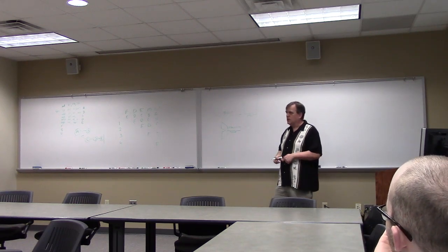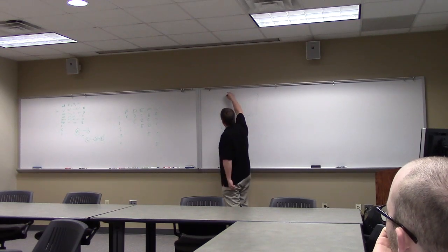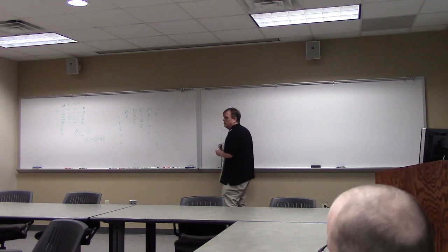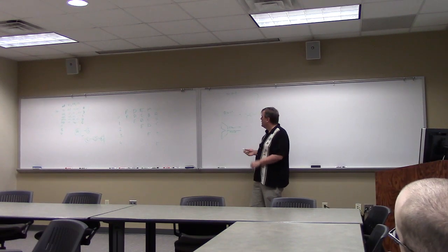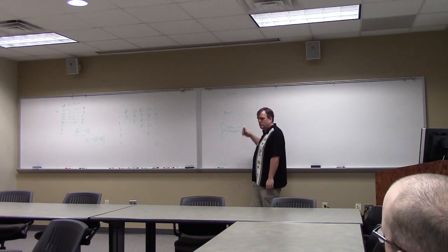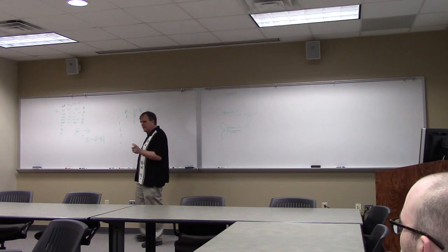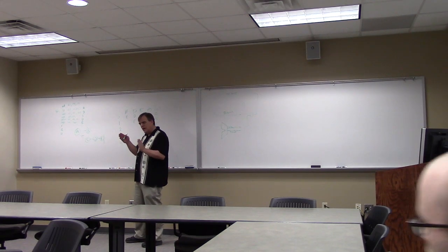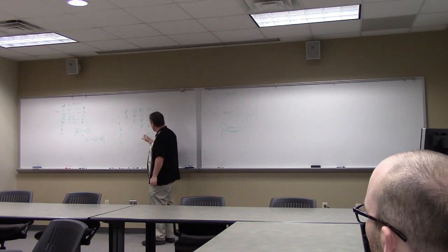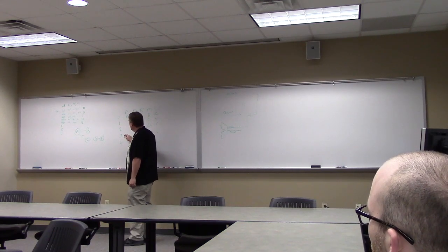And then that's the one that does the selection for PC source. This is the one that selects what goes into the program counter. So there's that one little AND gate just into your next stage. Depending on the delay on when the PC source thing locates, there might be enough time. But that means you're basically going to get your next one at this point if you're lucky. Let's assume we're lucky for the moment.